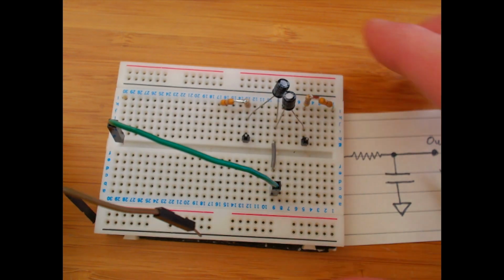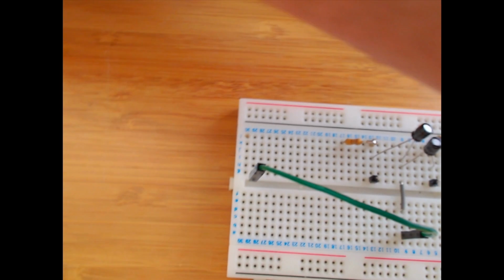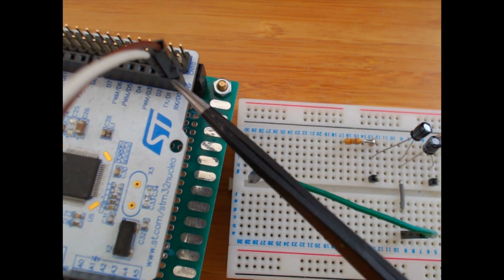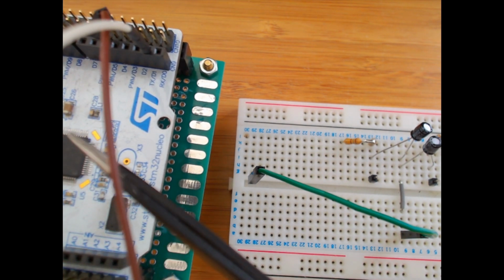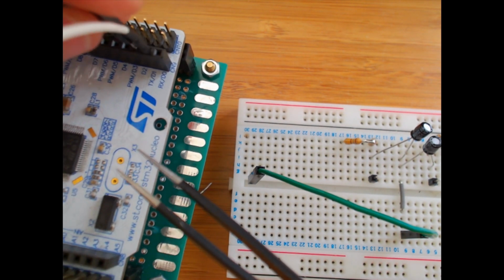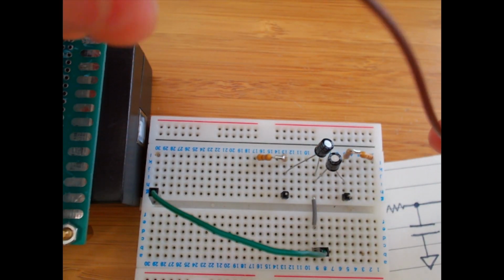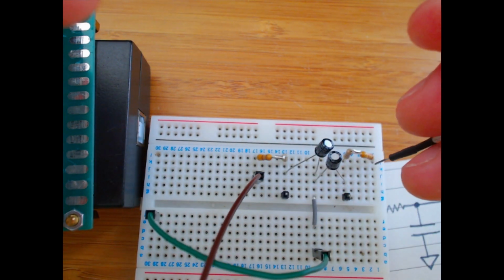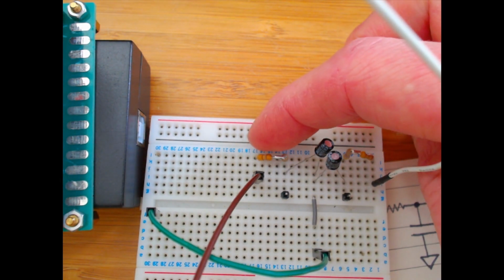So I'll just slide into frame here the development board. I'm going to unplug it for a second. This is the development board, and over here on these two pins we actually have the two PWM channels. So I've got these on a white cable and a brown cable, and they're just going to go into our 2 points. So let's wire those up, and I realize this is not great framing here. So we're going to come into this point, and we're going to come into this point, right? Our two filters. So this is channel 1 and this is channel 2.